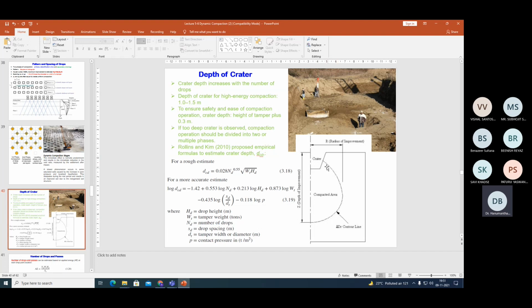It is obvious that the energy transfer happens in the form of a triangular load distribution or dissipation. So up to a certain depth it typically follows the triangular, thereafter there is certain dissipation. Or typically, if you take the bearing capacity theory or the pressure bulb theory, it is more like a pressure bulb. And you can use this simple equation for a rough estimate.